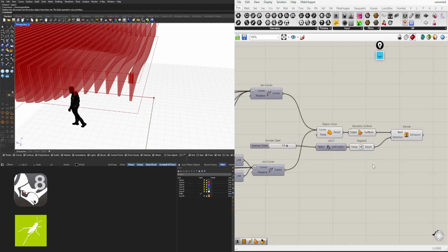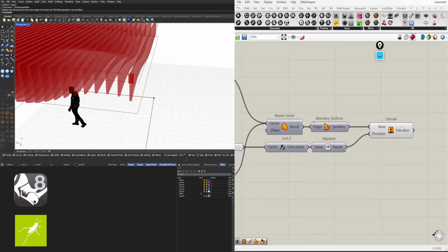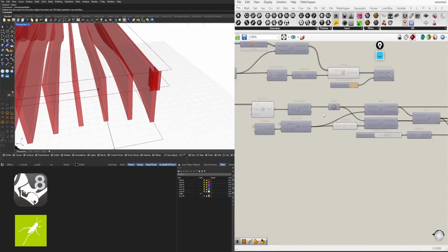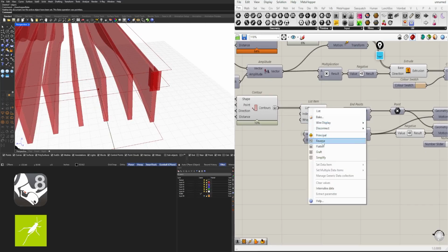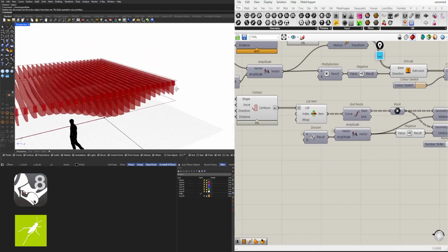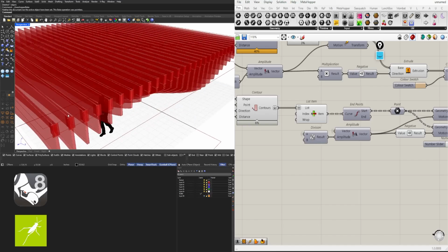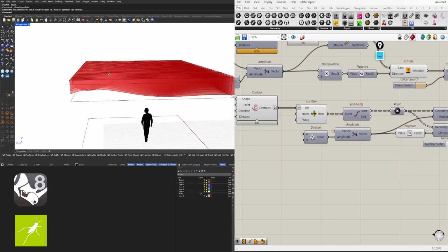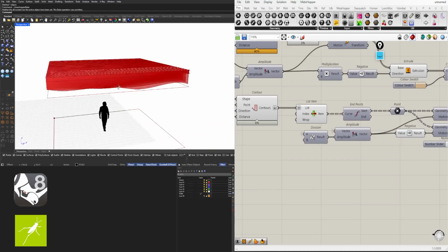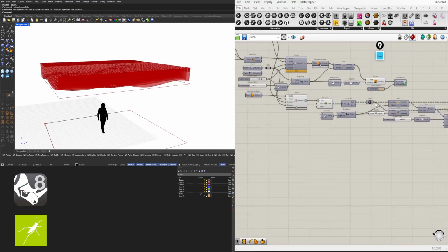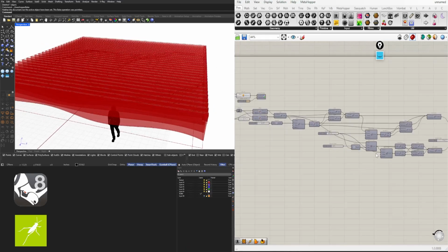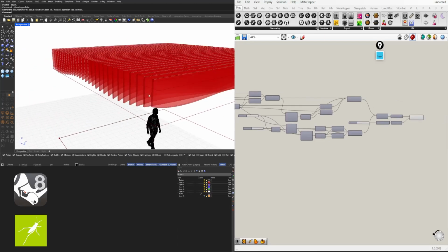So we're almost done here, but there's still something that you'll see that is a bit tricky here. So, okay, we've created the bracket. Now let's go here and graft this. Notice that it does it all, but it does it all to one side. Now, we can use a mirror command or a mirror component and mirror this to the other side, or we can also create all of this the same way that we created this, but on the other side.